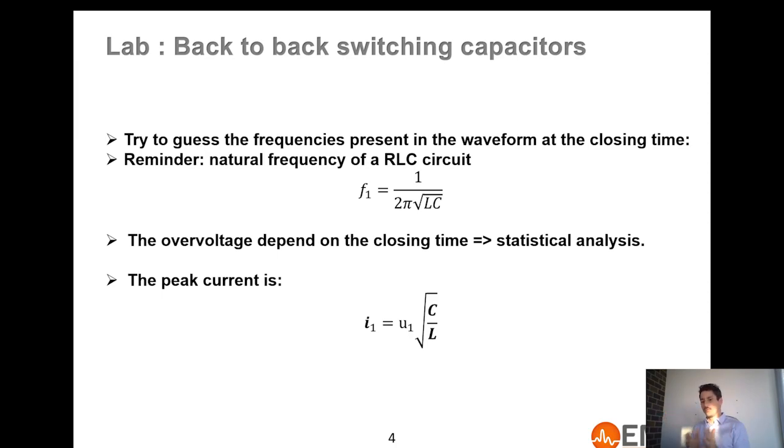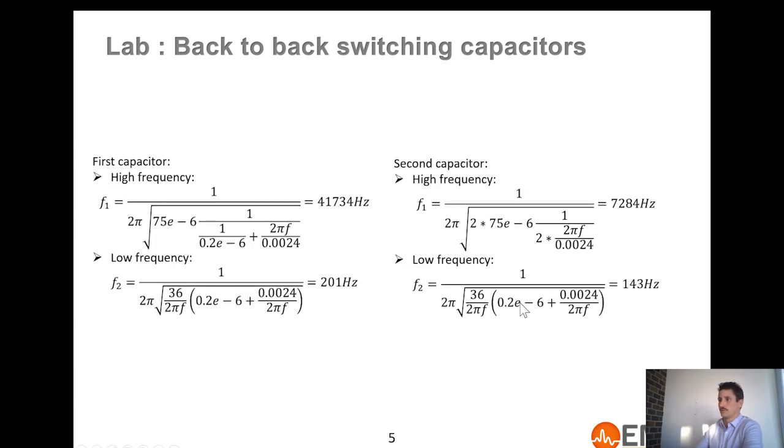And so basically you have to simulate sensitivity, and you have to do a Monte Carlo analysis and switch the breaker at different times on the period, close to the maximum voltage, close to zero, and anywhere else, but also simulate the imprecision in the closing time. Because of the mechanical nature, a circuit breaker may not always close at the same time. The three phases of the circuit breaker may not close exactly at the same time. There is a little mismatch, not so much, maybe 1 millisecond, but for transients it's very significant. So all that is being modeled. We'll discuss that in the rest of the insulation coordination course.